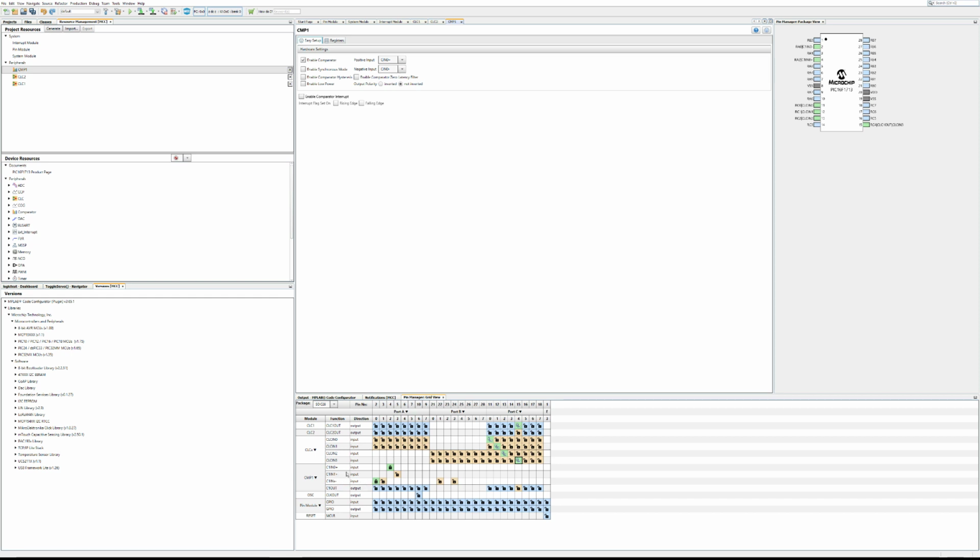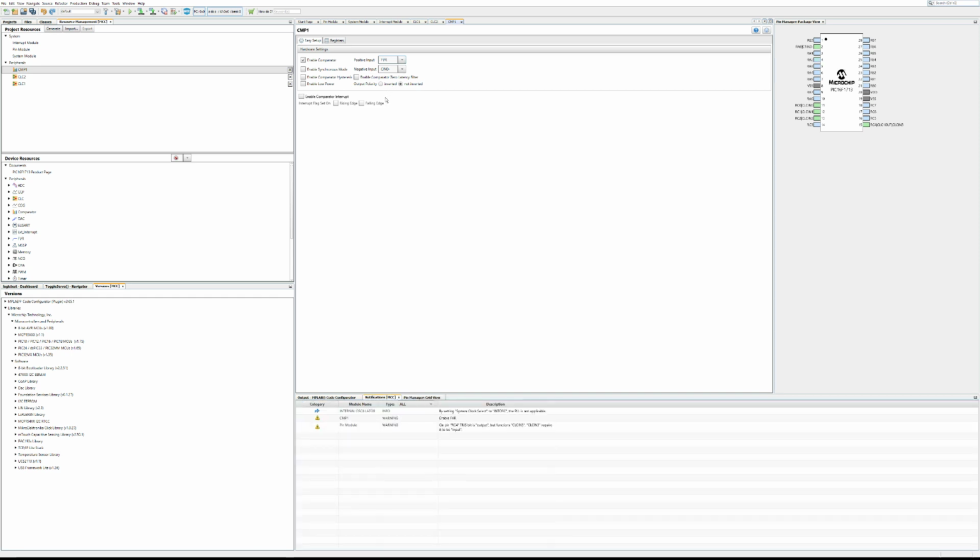Now, these can be remapped at runtime, which is why they have multiple, sort of like the CN0 plus and CN1 plus, even though this is all in C1. Now, you can also use, for either of the positive or negative inputs, the VSS or VCC rails. There are 2 internal DACs that you can use, and there is a fixed voltage reference, which is what you'll most commonly use for these parts.